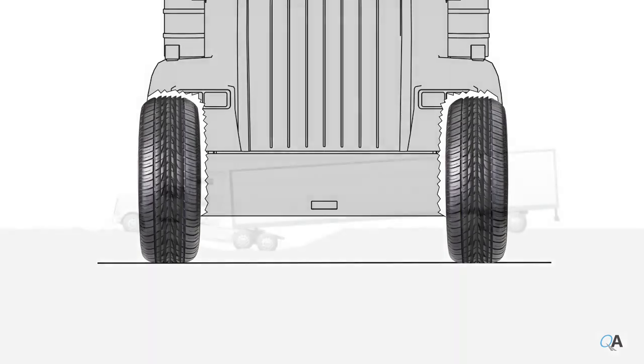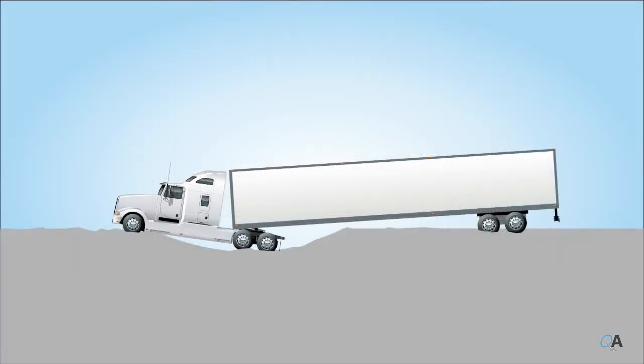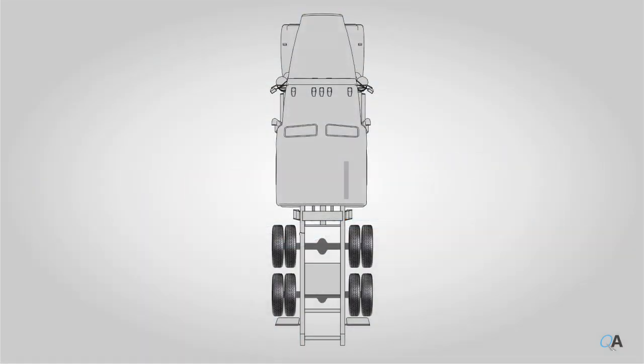Biased feather wear patterns may also occur from accident damage, such as when a truck drives down into a ditch. When the truck gets to the bottom of the ditch, the trailer will often hit one of the two frame rails and bend it downward. Even the slightest downward bend will cause the closest drive tire to carry more of the trailer load than the other three drive tires. The uneven load distribution can cause reduced traction and slipping in the three underloaded tires, while the overloaded tire has increased traction and tends to steer the vehicle to the opposite side.